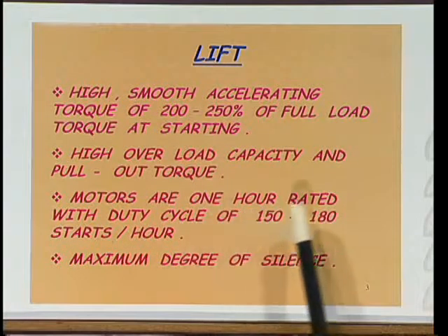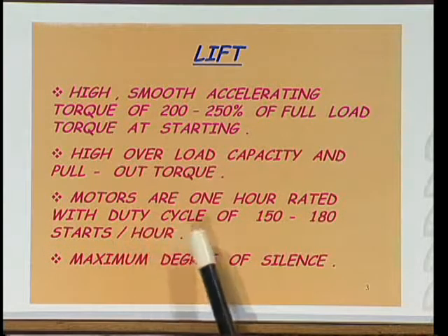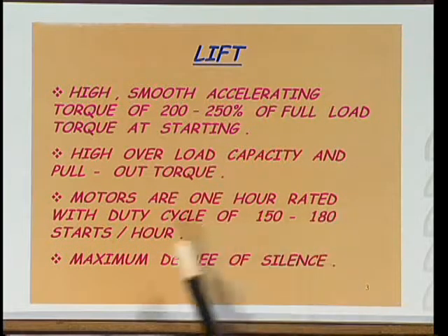Motors are 1 hour rated with a duty cycle of 150 to 180 starts per hour. The rating of the motor is normally 1 hour duration. The lift also comes under intermittent duty, that is, application of load for some time and rest for some more time. So the duty cycle or duty factor must be considered for the lift.